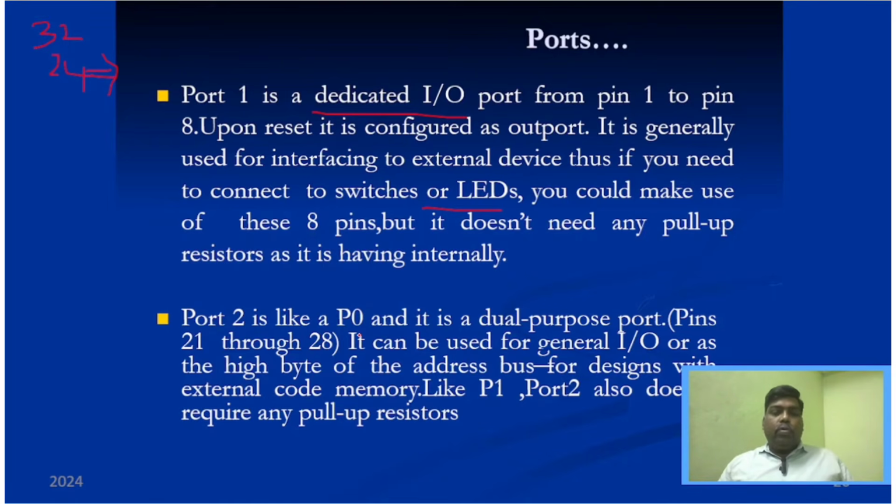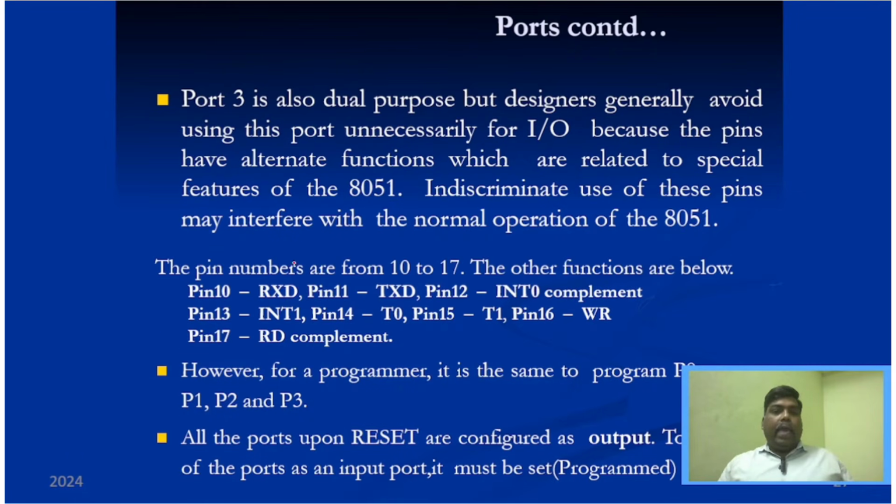And even port 2 will not require any external pull-up resistor. Only port 0 needs an external pull-up resistor, right? And port 3, you have to be aware of port 3 here.